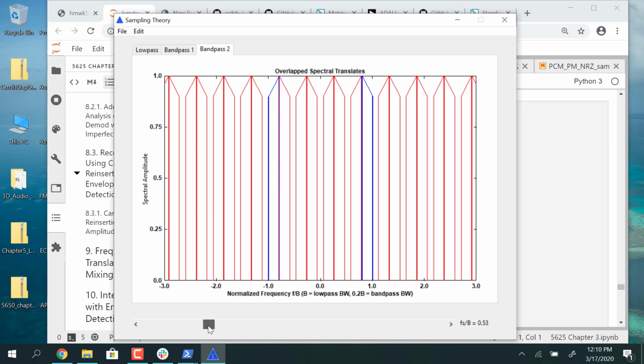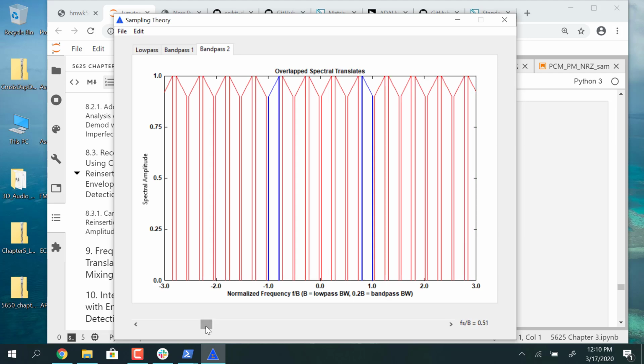But you can see that you can get by with lower sampling, and in reality, in software-defined radio, the undersampling operation is not to get back the blue signal, but to capture the signal that's right down here centered on 0 frequency. So we get frequency translation or frequency conversion and sampling happening all in one step.